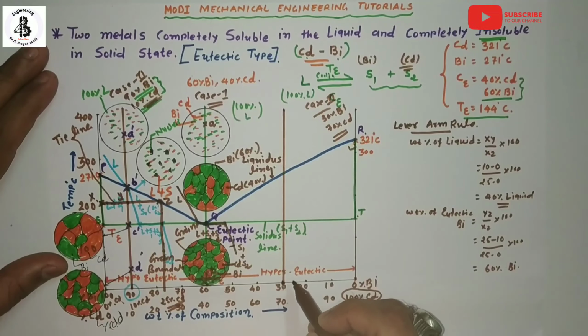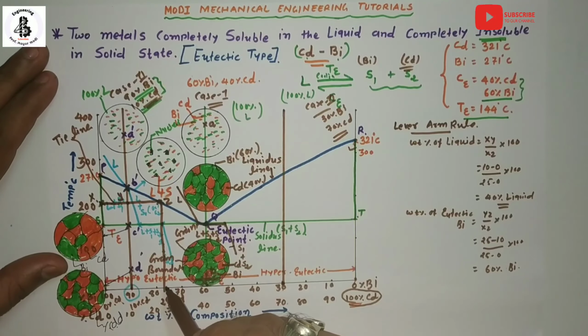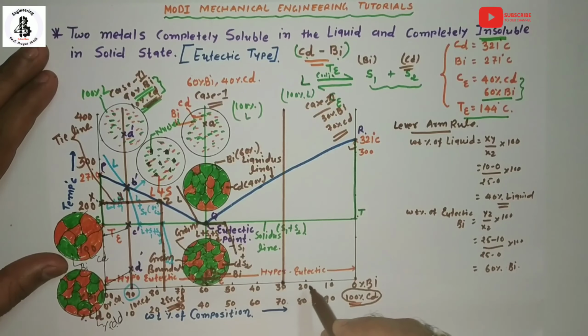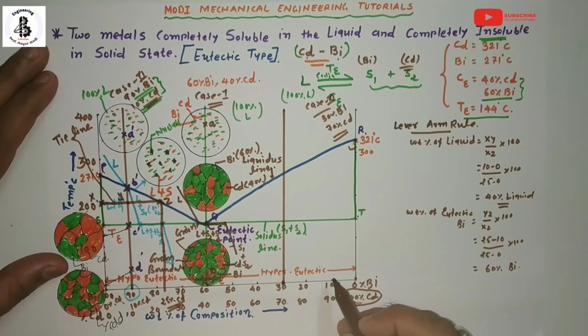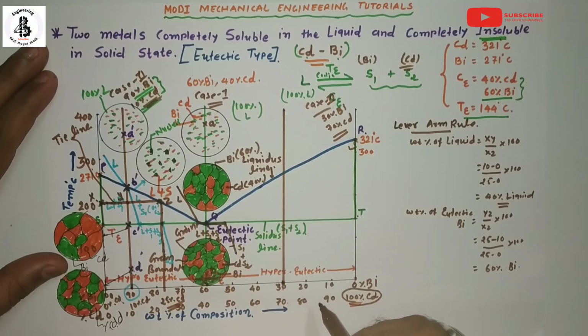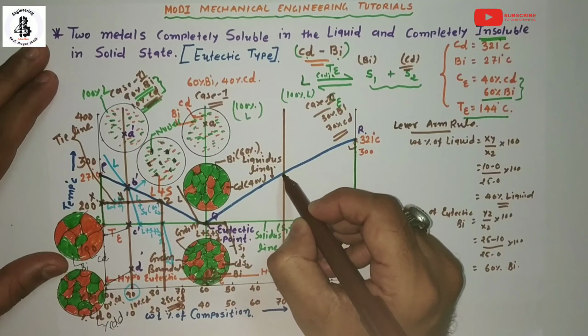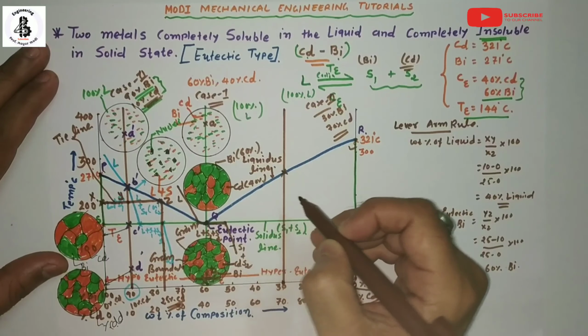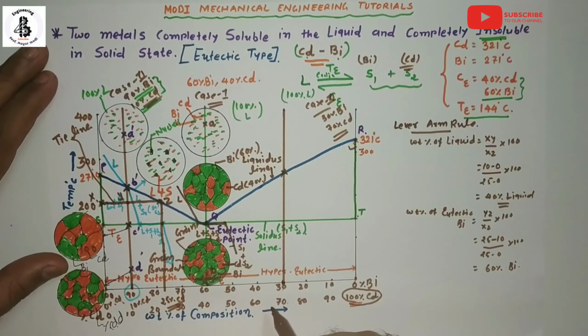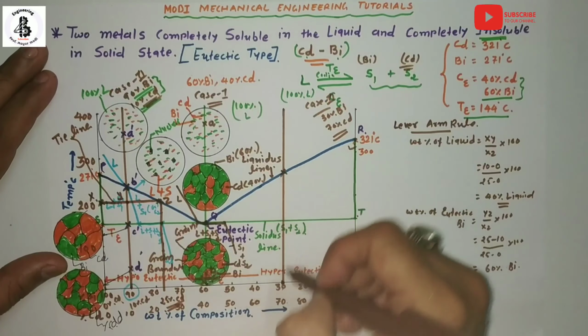Similarly to what we discussed for the hypoeutectic transformation, this is a hypereutectic transformation line. But here the enrichment by cadmium takes an active role in starting the solidification process at the intersection with the Liquidus line. So you can make different points.